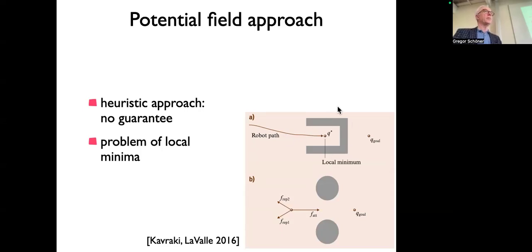often referred to example in this context called the chicken cage, where you would be attracted into this obstacle configuration because the target is behind it. And then you might get stuck here, and I'll say exactly in which sense. Or this could be an example where you might have a collision. You're familiar with the configuration from the attractor dynamics approach, right? And there could be situations where the repulsion here, this vector is the repulsion from this obstacle, this vector is the repulsion from that obstacle, this is the attraction. If you don't do that right, then you would press through, even though you might potentially collide.